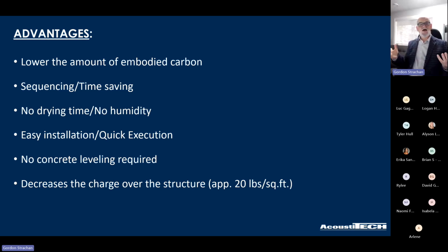So when we're talking weight, concrete topping, gypcrete topping, 18 to 20 pounds per square foot. The dry toppings we work with are from 2.2 to 5 pounds per square foot. Amazing drop in structure weight. When we worked with Woodworks BC on some calculations, their engineers said that reduced the structure weight by half. That's no joke. Cutting the structure weight by half is a serious, serious move. It's taken things to the next level.